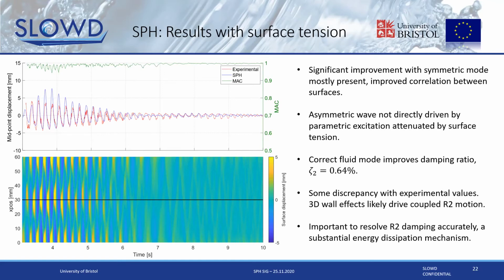So we don't include the large front and aft walls of the tank, and these have significant area. These are about 2/3 of the vertical wall area that aren't included in the simulation. And these present an interface where the fluid free surface is shearing up and down against these walls. Because we're not including that shearing force, we may not resolve that important forcing that drives this damping behavior.